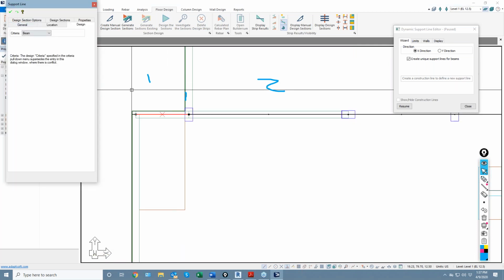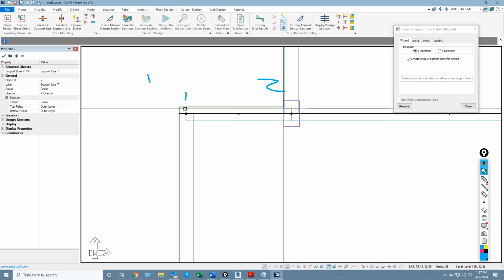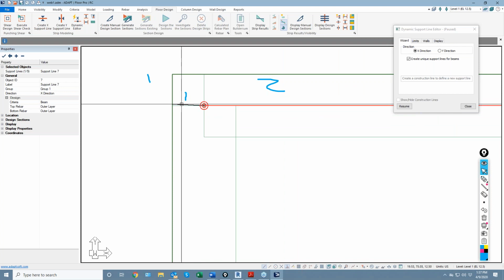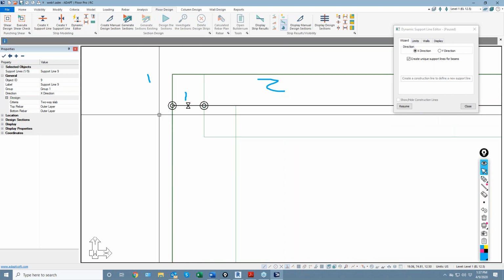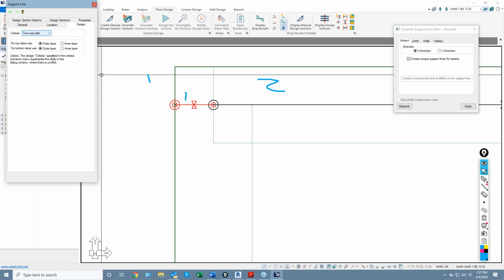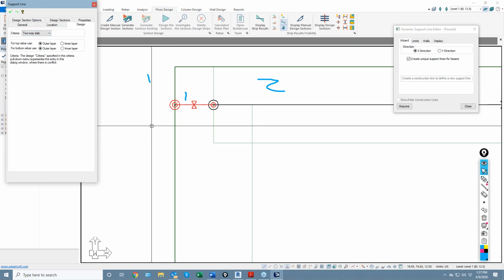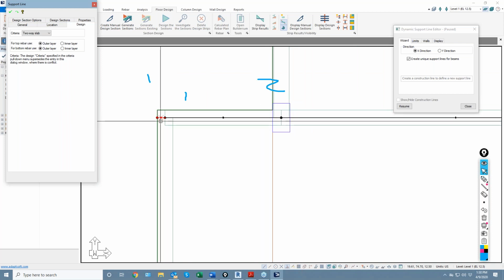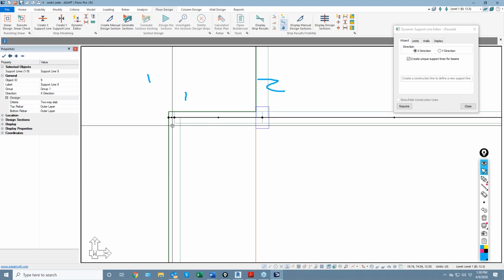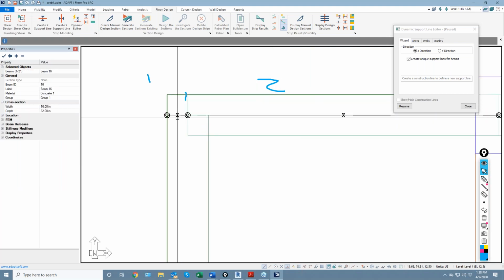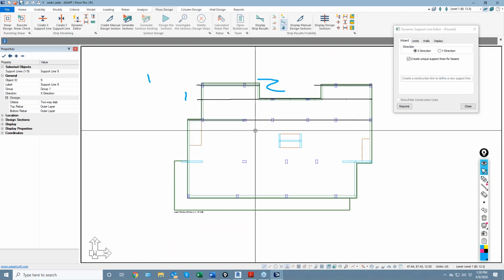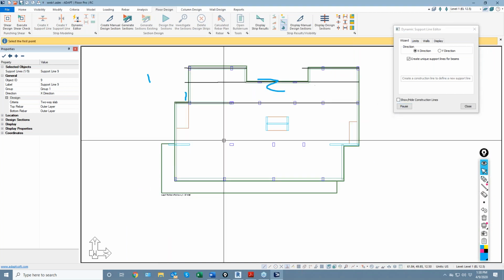and also a beam criteria there. Now, one thing you have to deal with in this case, because my beams are modeled away from the slab edge, it actually creates a tiny little support line even here. This is considered two-way. There are no real adverse issues with this. It's a little bit annoying just because you have to deal with it. Had that beam been modeled out to face, I wouldn't have that segment. So keep that in mind. I'm actually going to just delete it out so we don't have to deal with that. If I manually created this, I also wouldn't model that tiny little segment in that zone. So let's go back and continue on.